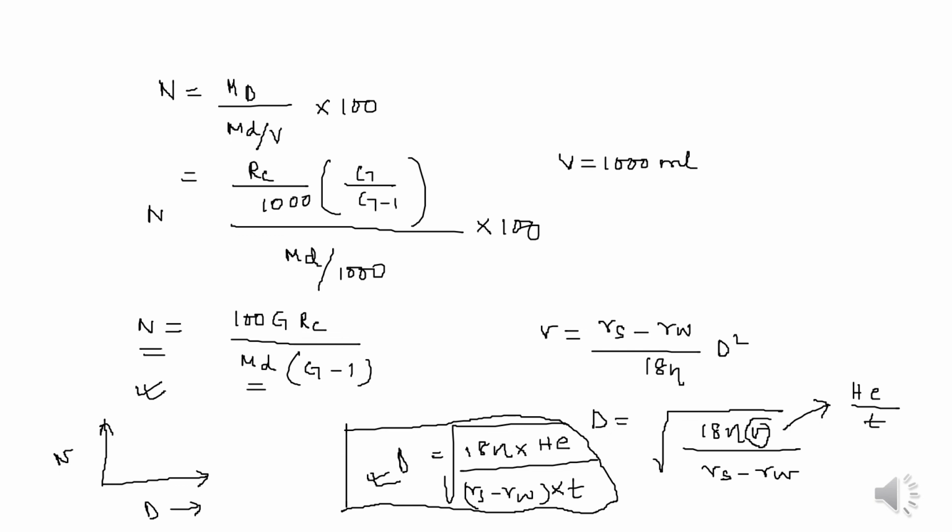Like we also consider the coarse grain soil that has been retained on the 75 micron sieve. So we also take the percent finer of those particles and the diameters corresponding to it, and also we determine the particle size distribution of this fine grain soil, and accordingly we plot it together, right? So we will talk about this grain size distribution curve in more detail in part 2 of this lecture. So thank you for today.